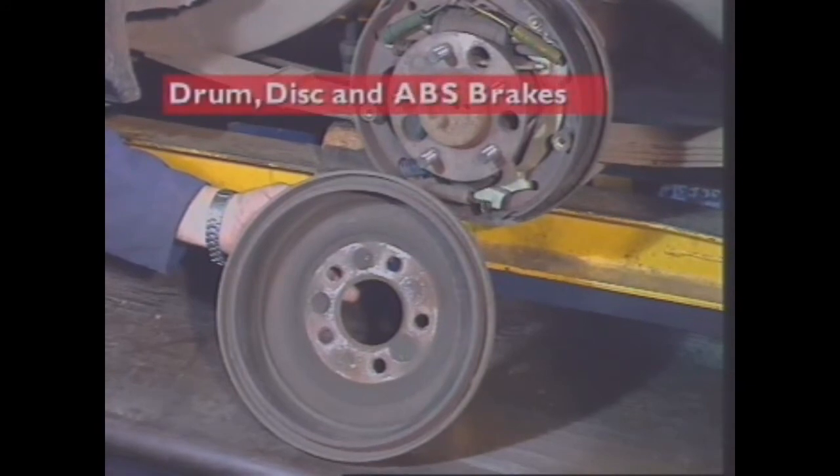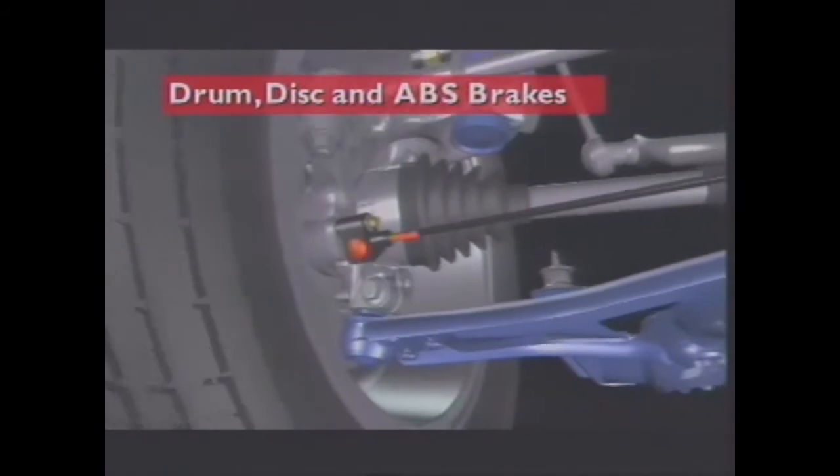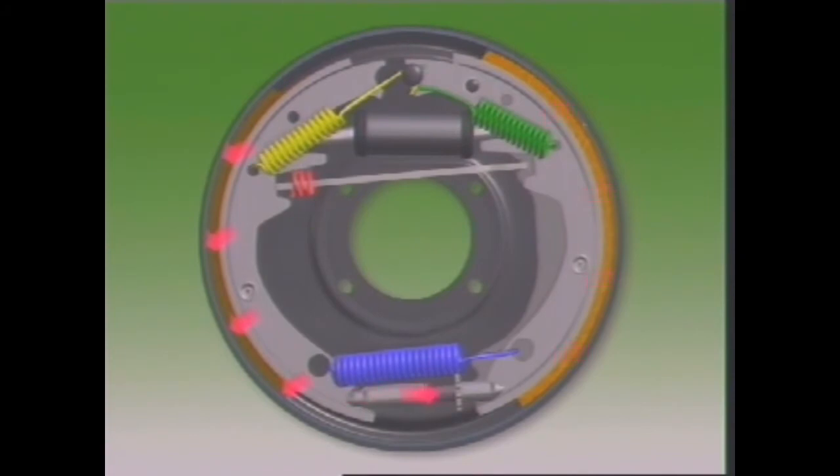This section examines drum, disc, and anti-lock brakes. Drum brakes have a drum attached to the wheel hub, and braking occurs by means of brake shoes expanding against the inside of the drum. With disc brakes, a disc attached to the wheel hub is clamped between 2 brake pads. On light vehicles, both of these systems are hydraulically operated.